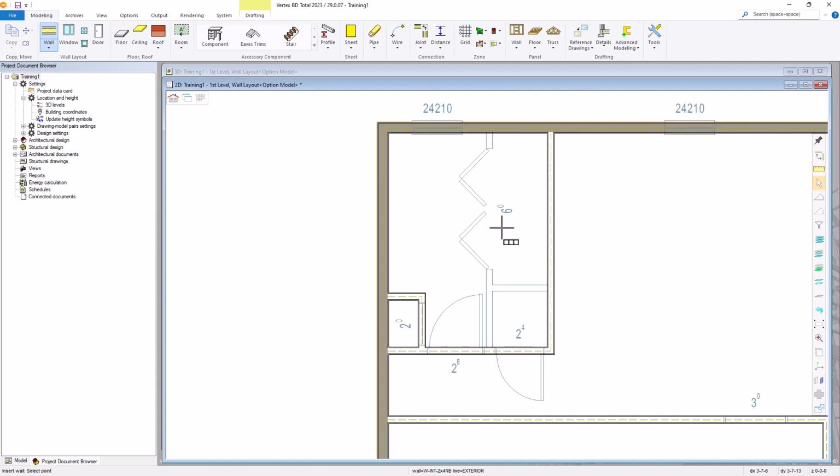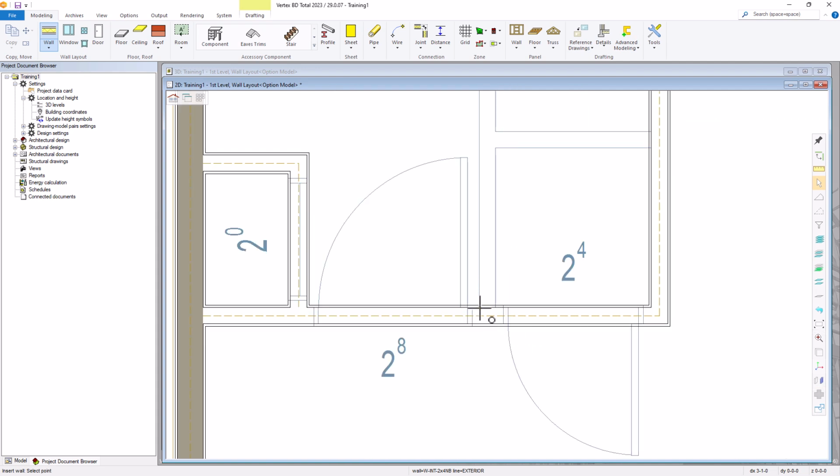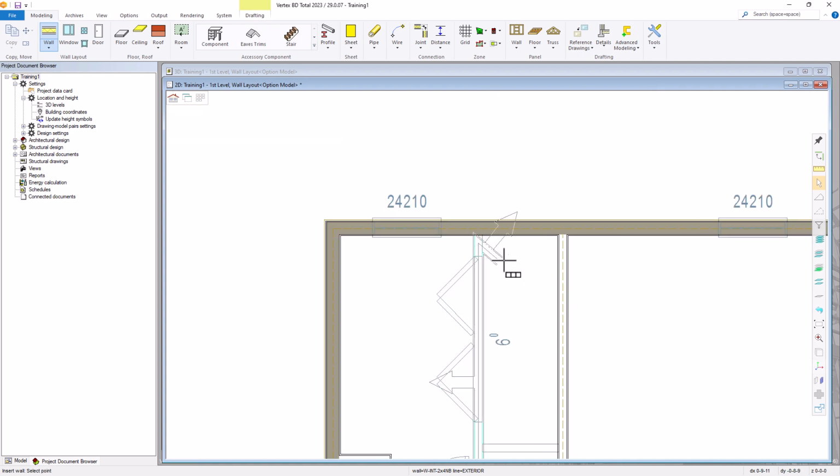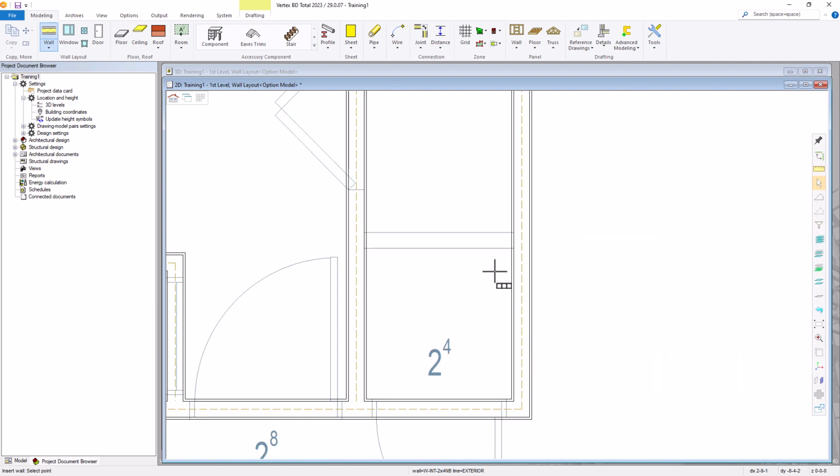Now let's work on this second section here. I'm going to pick this wall. Let's lock that into vertical. Go to the opposite corner. V to confirm. Let's go ahead and add this one piece here. Lock it into horizontal. It's straight. V to confirm.